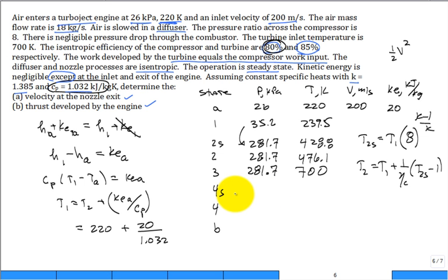And now we go to the turbine. In the interest of time, I have to stop here. Sorry, wasn't able to finish it. But what's a tricky part about this turbine is you start the calculation saying the work that I need to drive the compressor, I now know. It's the work that I need to get out of the turbine, which is an unknown. And now you work forward.